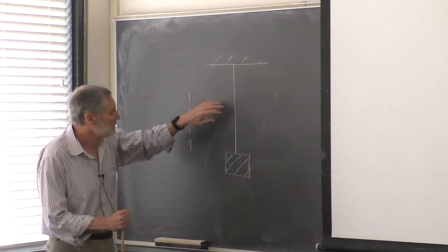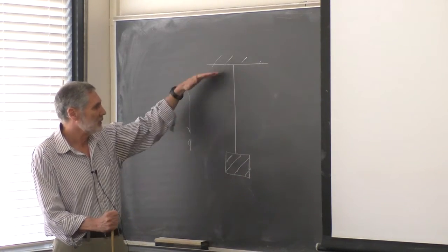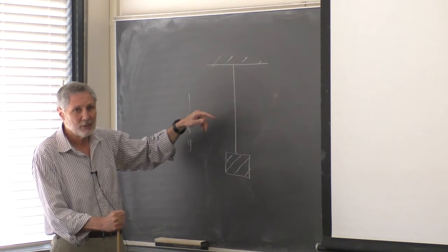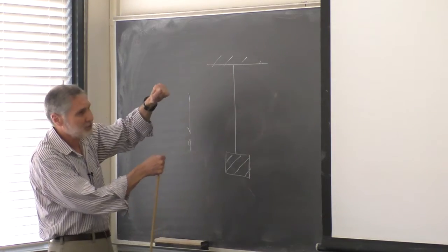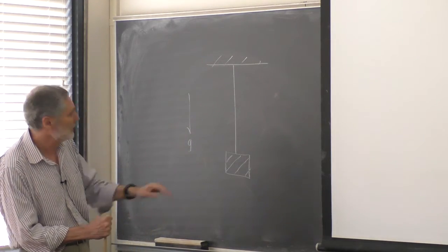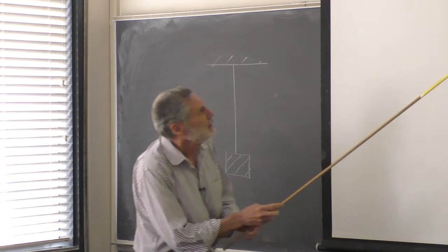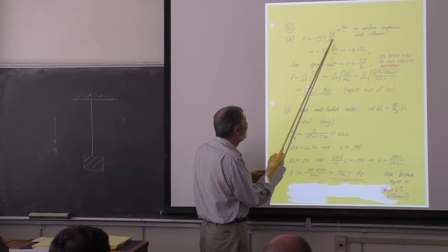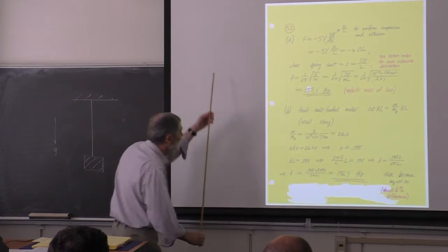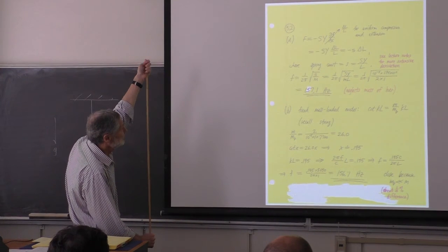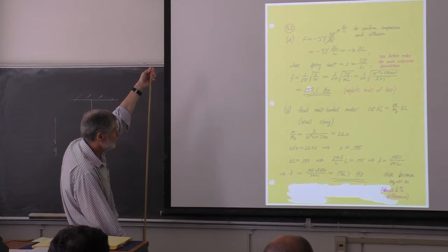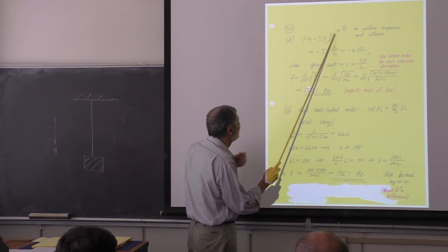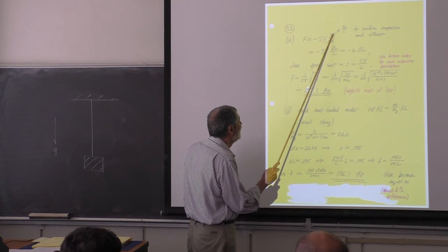Because the mass is light compared to the bar, the speed of waves is relatively very big here. So we're going to get approximately uniform expansion and contraction when this thing oscillates. And in that case, the displacement here, remember, is c. When it's uniform compression and extension, this is the strain, the dimensionless strain. I can just evaluate it.